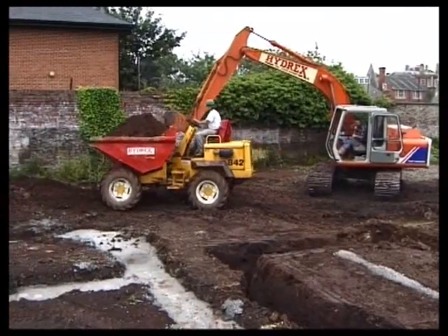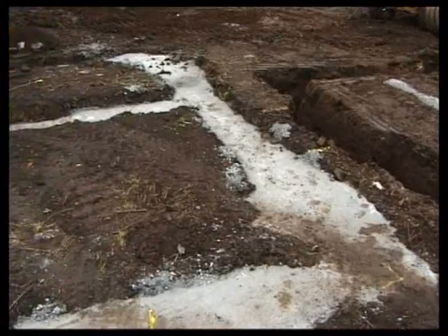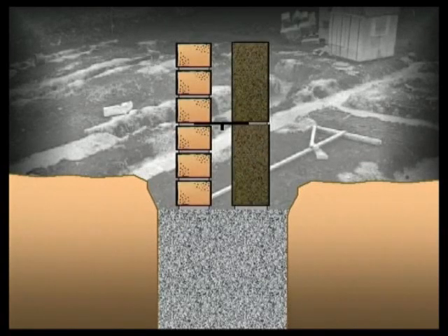Most houses have strip foundations. As the name implies, this is a strip of concrete supporting the load-bearing walls. The width of the strip depends on the nature of the ground and the load of the building.